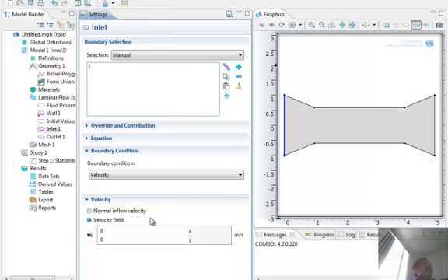A velocity field means it has two components. You can specify if you expect the inlet flow to have both an x component and a y component velocity, meaning that the velocity vector is not straight but at an angle. Then you will specify both vx and vy components here as a function of y, if you so choose. So be bold, ask questions, click everywhere, and learn.